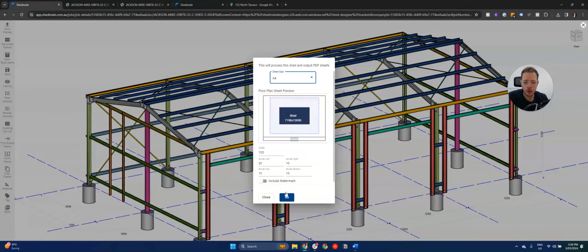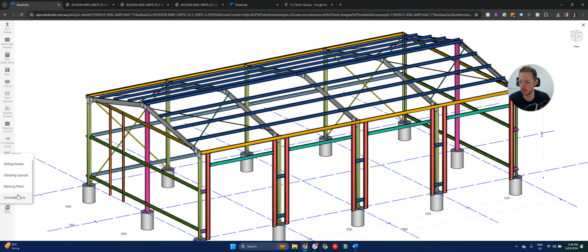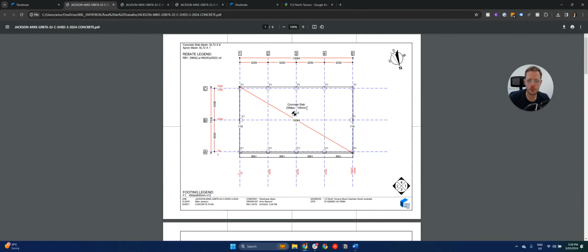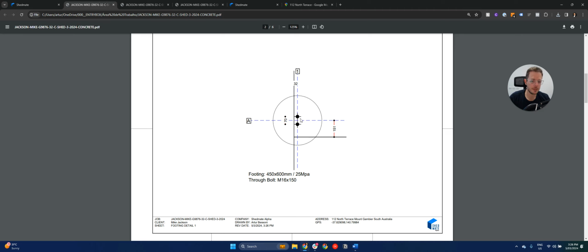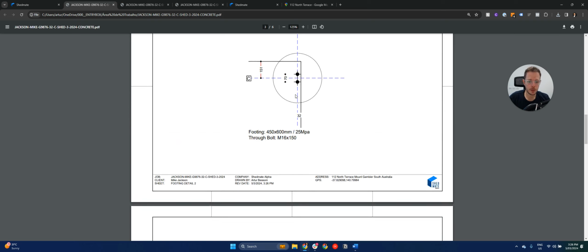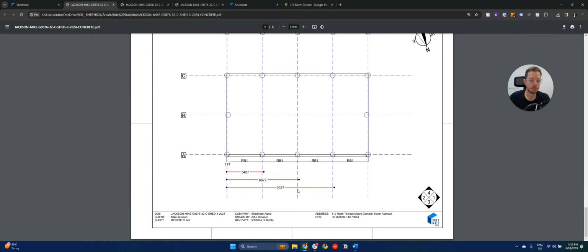And I can actually create another concrete plan. So what's the difference? Now that I have the hold down bolts, or the base plates, I know how my concreting plan is going to behave in a more precise way, so I can create better concrete plans. I could recreate the architectural plans from here as well, but just showing, I have here my concrete slab, and it's a lot more detailed than the previous one. If I see the other pages, I know exactly where to drill here to put my bolts, and everything is very detailed in this specific one, even the concrete apron and the rebates.